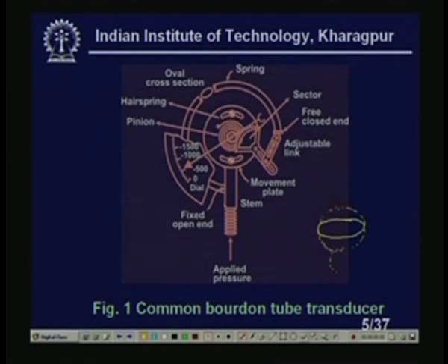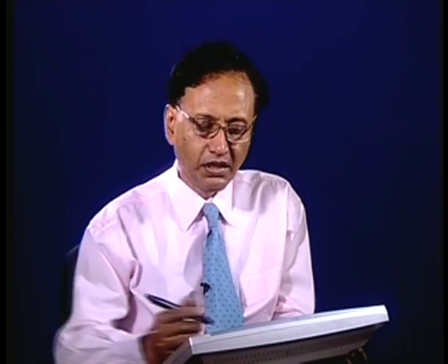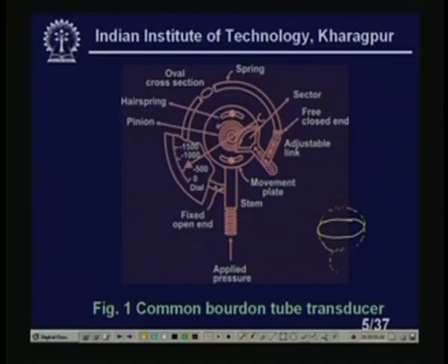It is a very widely used transducer, I should say, for industries. Everywhere, from a cycle store to any process industry, you will find it. It has a very wide range. It can measure the pressure of corrosive liquids, and gas also. Starting from liquid, gas, air, everything we can measure with this. Over the years people have been using it, even though this is basically a monitoring instrument, not a transmitting instrument. Since the tube is a C, we call it the C-type Bourdon tube,